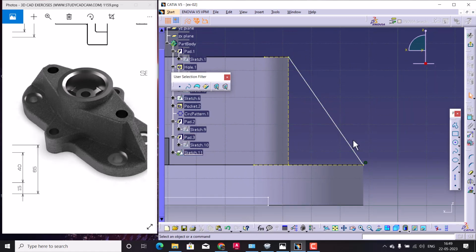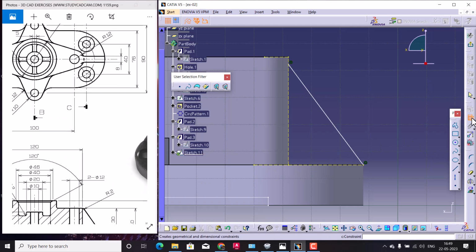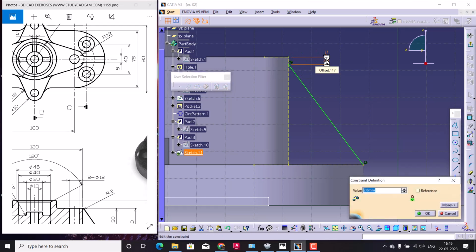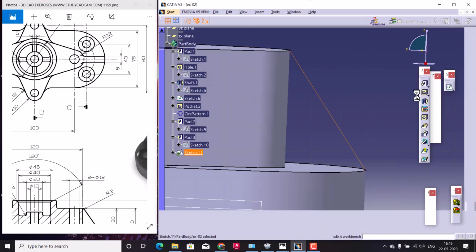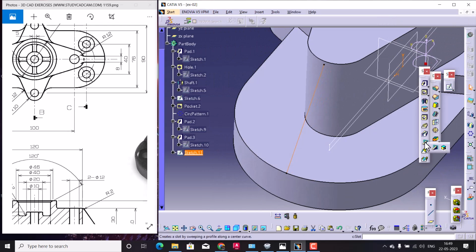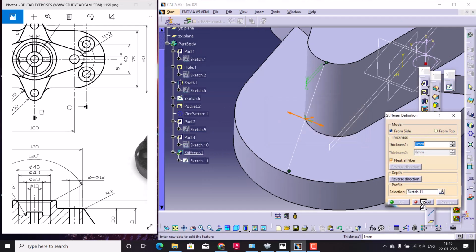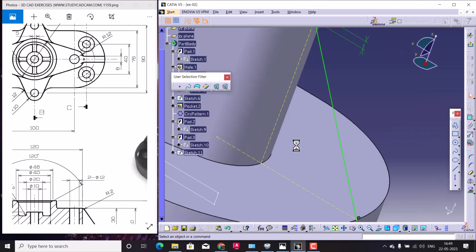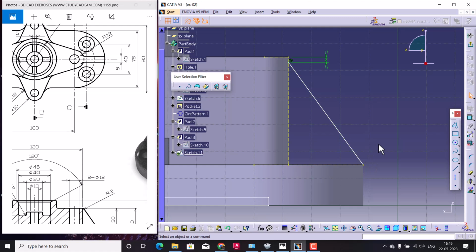So instead of coincident exactly with the point, let us try over here, coincident with this. I guess the thickness is just 5 mm. Our thickness is 8 mm. So let us keep it at an offset of 2 mm for now. Same thing, we have to do it at the bottom also. So instead of making it contact exactly at the extreme, we need to keep it with some distance.